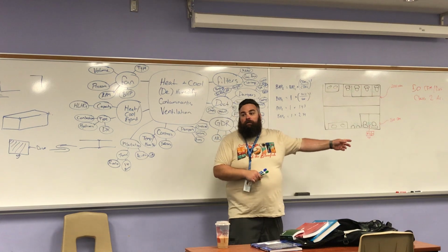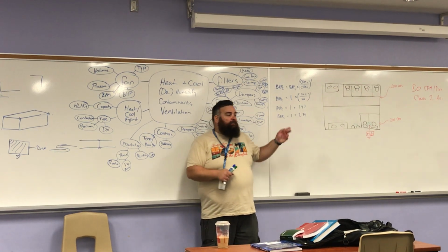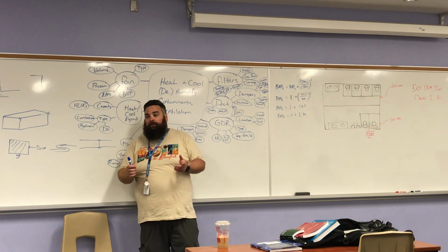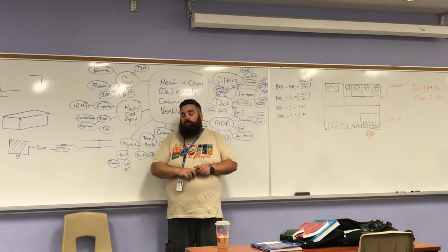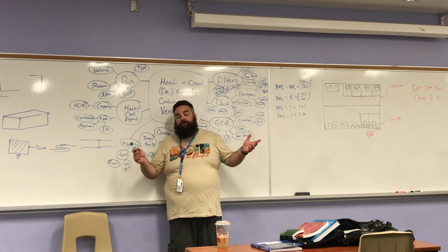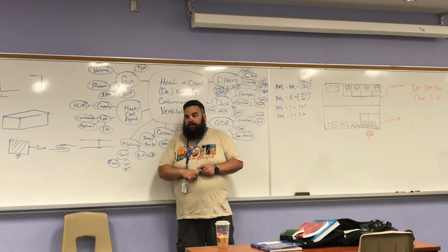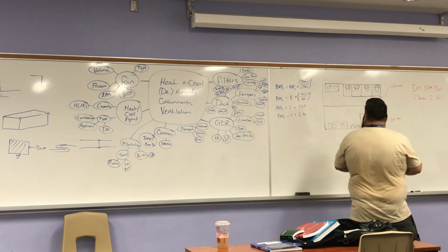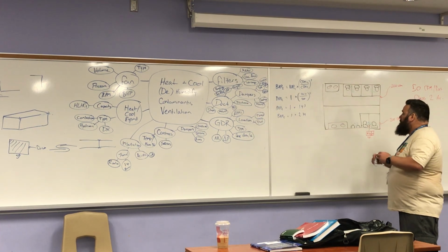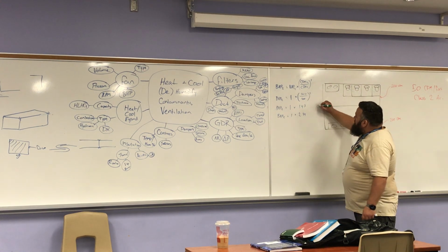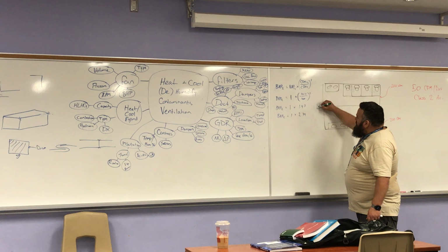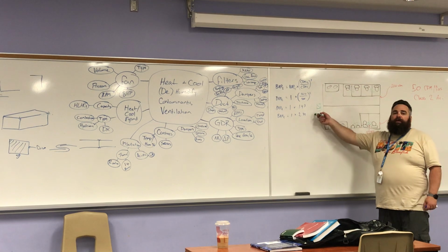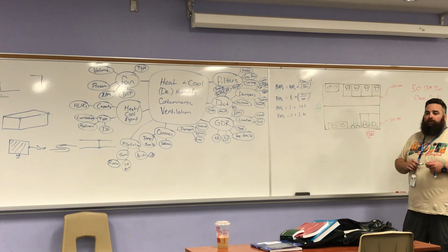I'm gonna make an executive call. I'm gonna say we're gonna go up through the roof. Part of the benefit from that is we don't see the termination from the ground, so architects like that. We're not super concerned with bringing in outdoor air because the roof's potentially a big area. We'll make sure that we keep 10 feet of clearance to any intakes, and we'll note that on the drawings. But let's go with that. So what I'm gonna do is I'm gonna show my fan right here, okay? I made a call just for the sake of this example. That's a roof-mounted mushroom fan. My fan's up on the roof, okay?